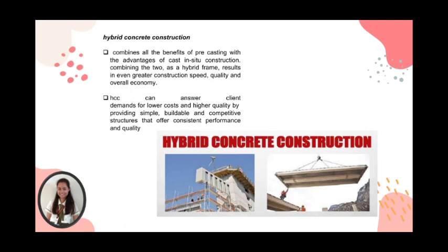One of the modern methods is the hybrid concrete construction. It is a method of construction which integrates precast concrete and cast in-situ concrete to make best advantage of their different inherent qualities. The accuracy, speed, and high-quality finish of precast components can be combined with the economy and flexibility of cast in-situ concrete. Hybrid concrete construction produces simple, buildable, and competitive structures. The client is given better value, and the contractor benefits from increased off-site components manufacture, safe and faster construction, and consistent performance.